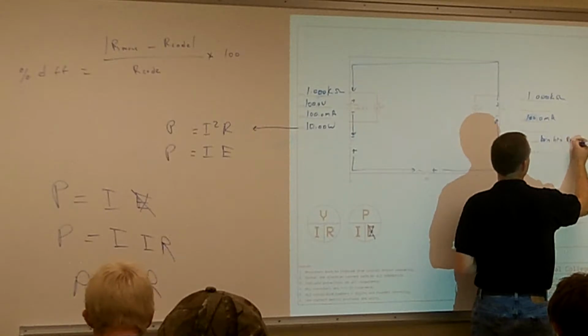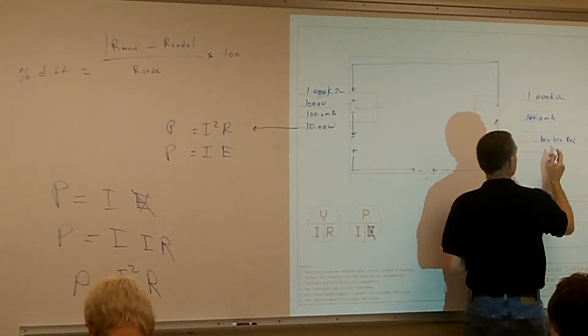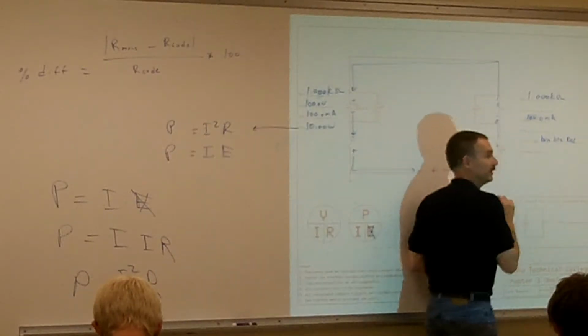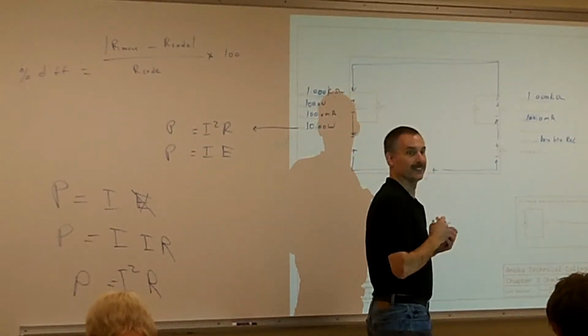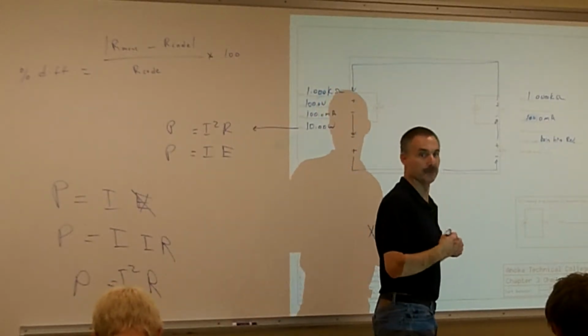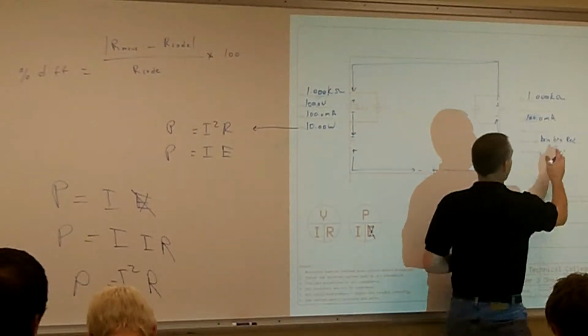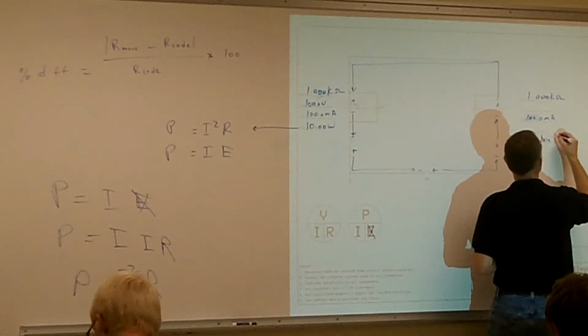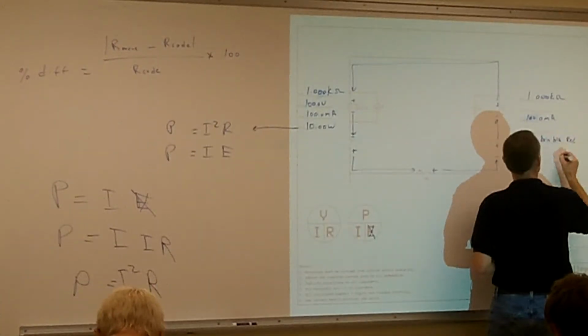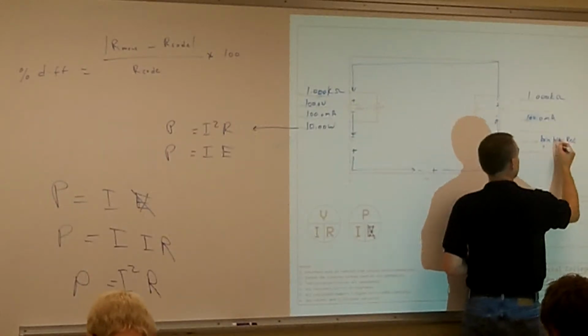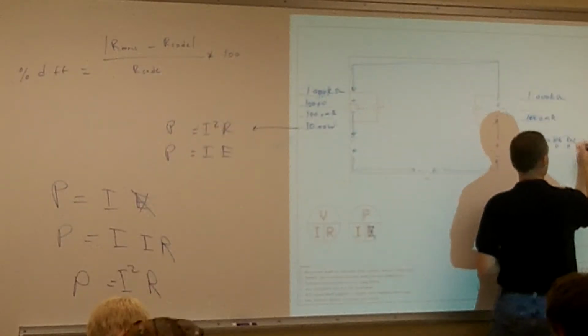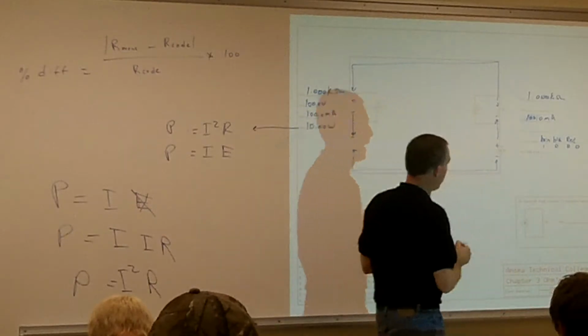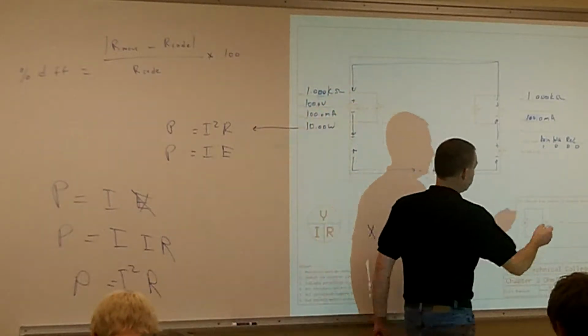Brown, red? Brown, black. Oh, brown. Yeah, you're right. Brown, black, red. Yeah. Black is 0, so it's brown 1, 0, and then 2 more zeros, 1, 2. So brown, black, red, and then we know it's gold.